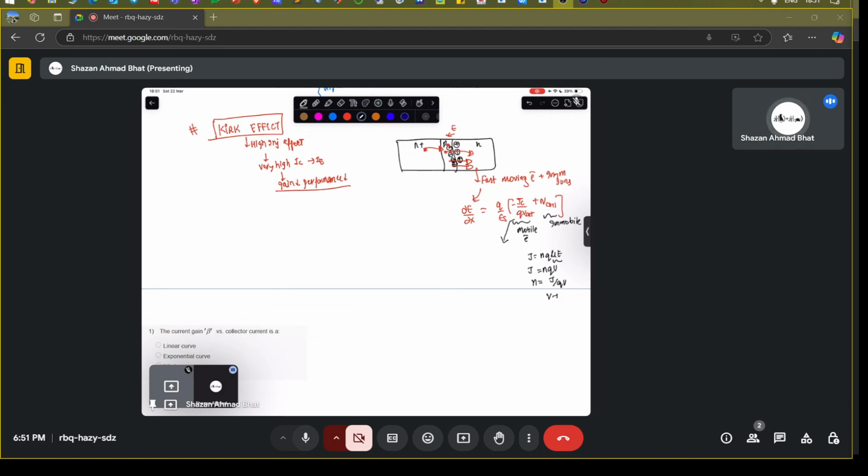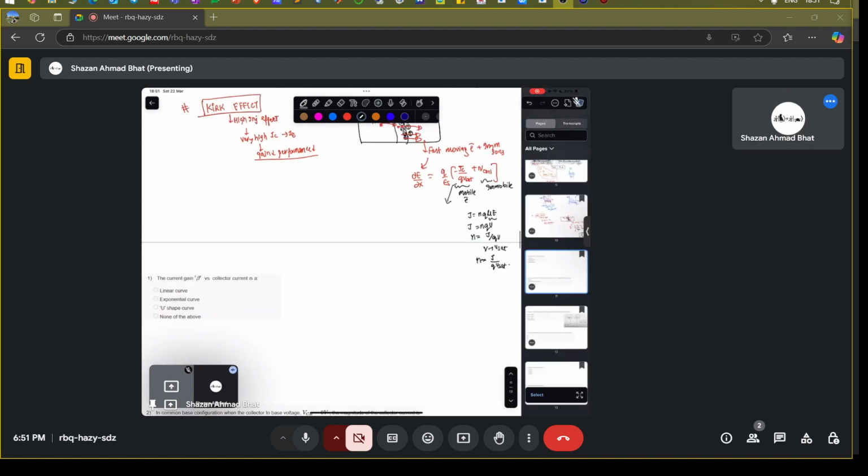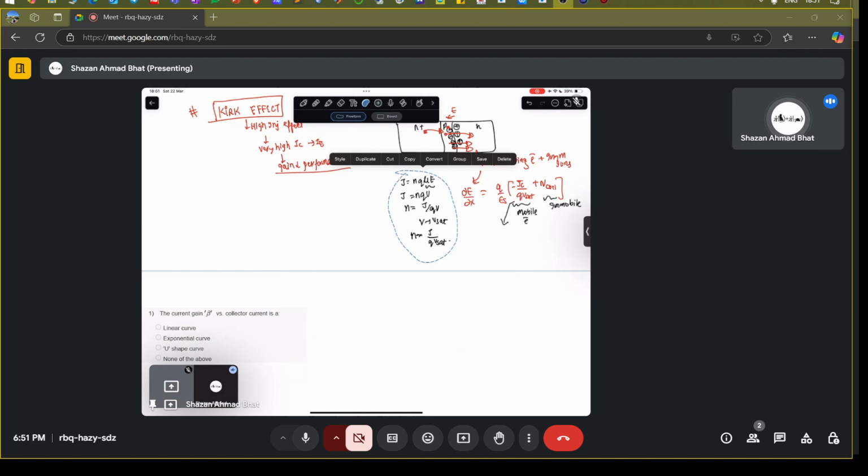If the velocity reaches the saturation velocity, which happens at these regions because of the huge electric field, then you have n equals J over q times the saturation velocity, and you already have a negative sign in front of this. Now what is going to happen?